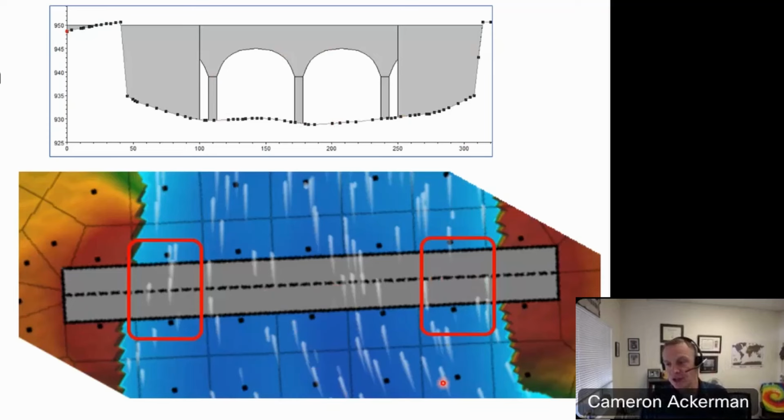As I turned on the bridge, this is just water depths, and then I turned on the velocity tracers. And you can see based on the velocity tracers, the engine doesn't know anything about what's going on underneath this bridge deck, as blocked out by these abutments. So I've got these abutments where I should not have any flow out here. RAS doesn't know that.